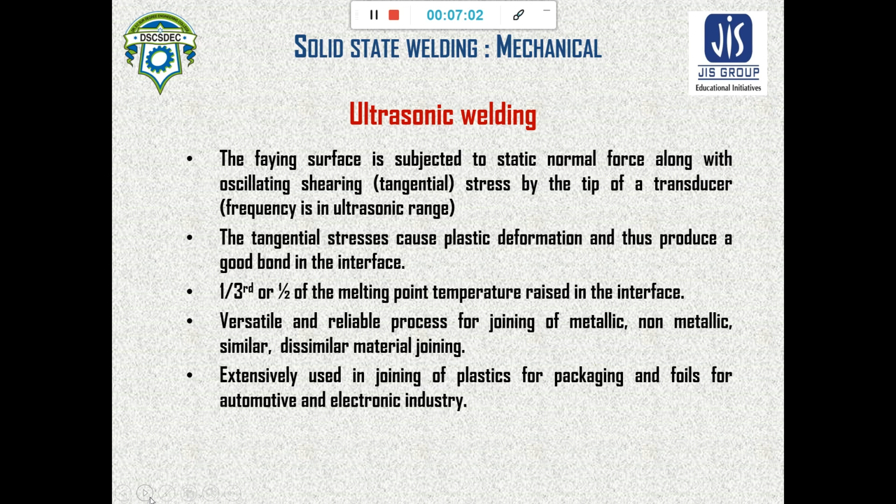In the faying surface, a good bond in the interface may be created, and that bond is created at a temperature one-third to half of the melting point temperature. So the temperature rise in the interface is very low, and it is much less than the melting point temperature, so there is no chance of melting the material. That's why in the solid state, good bonding strength can be achieved by this process.